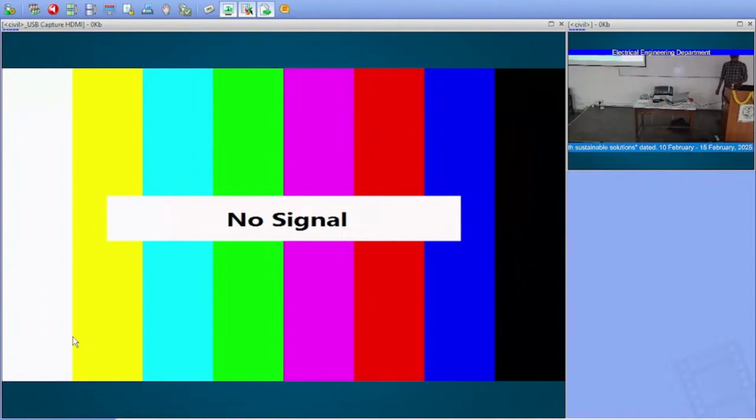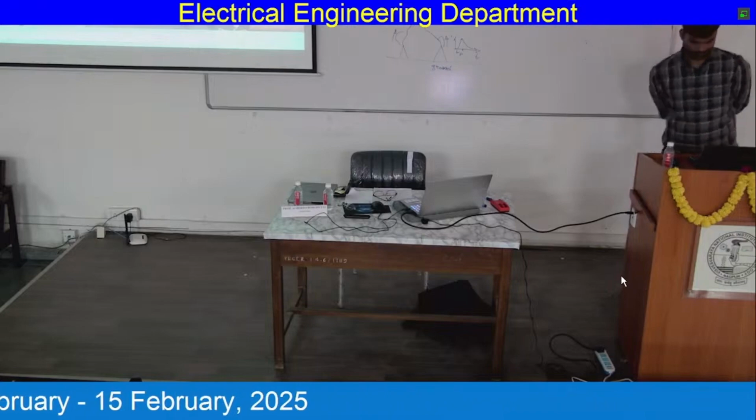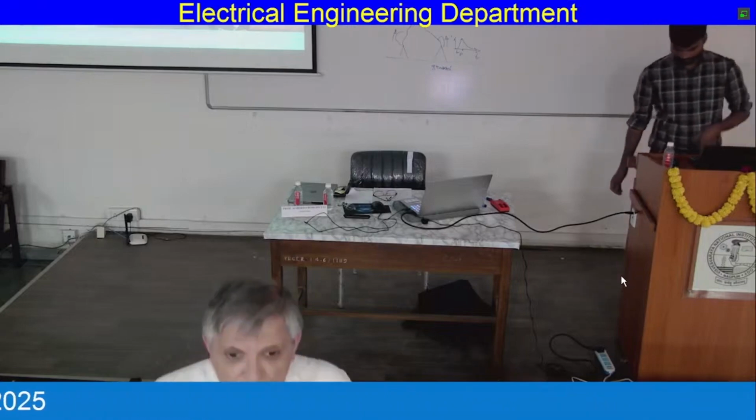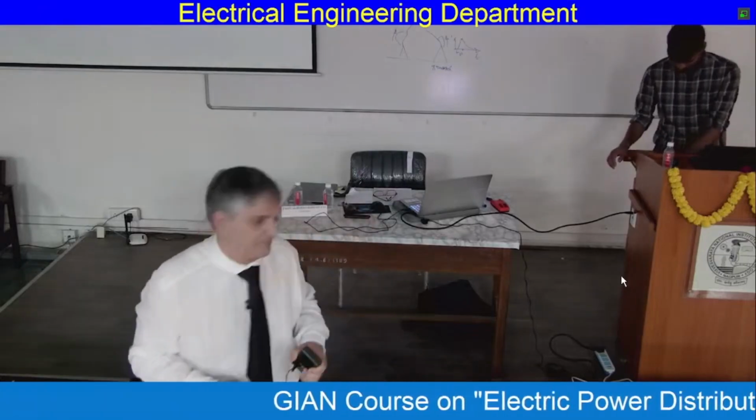There are sensors in various locations that are sensitive to these events, in particular to the electromagnetic field produced by the stroke. So they can evaluate the intensity of the stroke, but also can localize because of the several antennae. And they can make a triangular calculation, and so they can provide the location. So this is the so-called lightning location detection system.